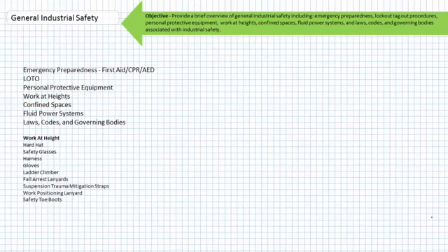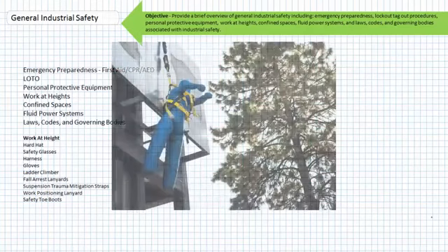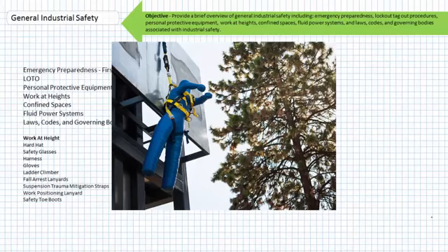A fall arrest system is required if any risk exists that a worker may fall from an elevated position greater than that of 6 feet. Typically, a fall arrest system is composed of a harness and a shock-absorbing lanyard. Ideally, the fall arrest system should only come into service should a fall occur. Bottom line up front, wearing a harness will not prevent you from falling. It will, however, mitigate the effects of a fall if combined with a shock-absorbing lanyard and a solid anchor.